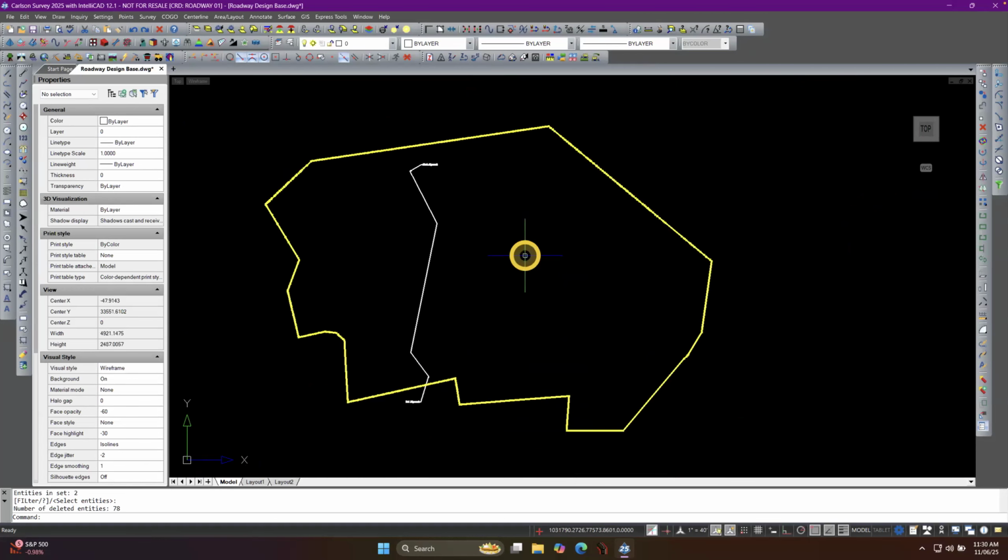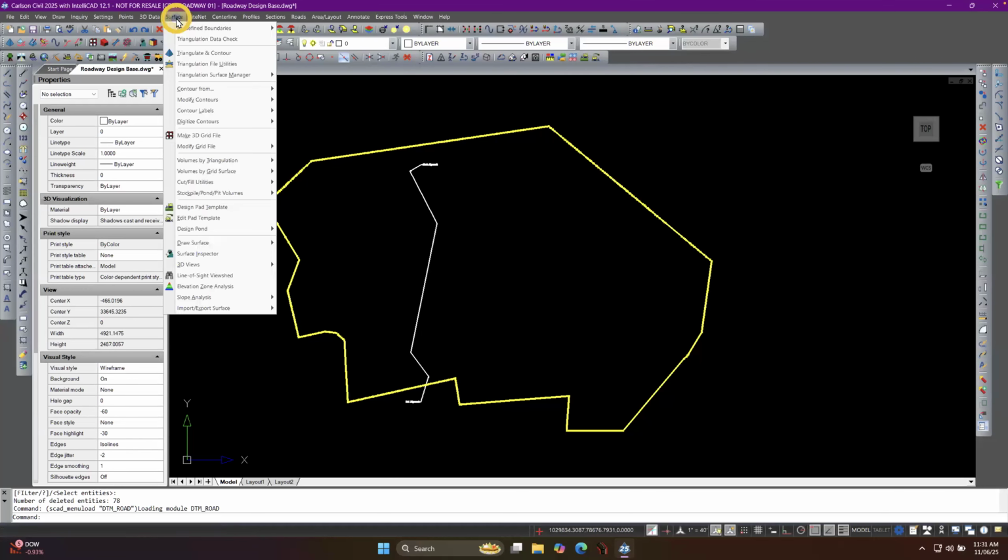And, oh no, where's my surface? Well, your surface is safely in that file that we saved when we did the import of the Civil 3D data. And so we can get that back. Let me switch to my Civil module just so we're all on the same page here. So if I'm in Civil and I want to recreate those contours, I'm going to go to my surface menu, which is right here past the 3D data menu.